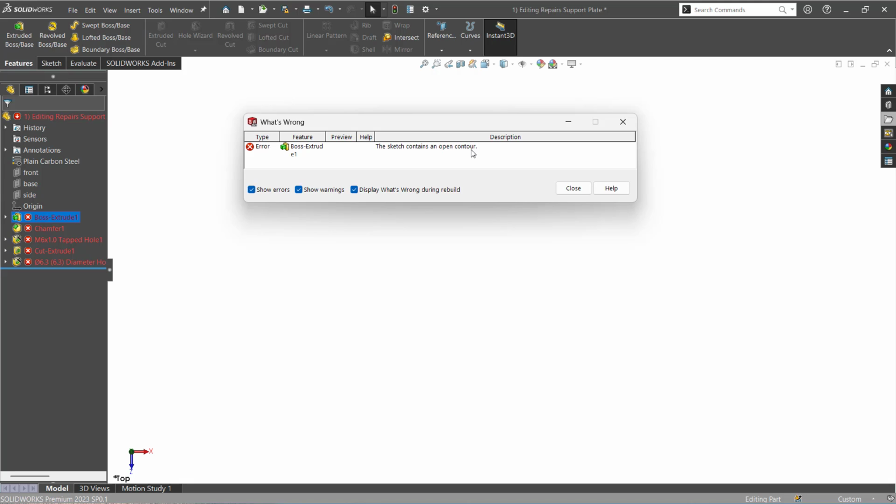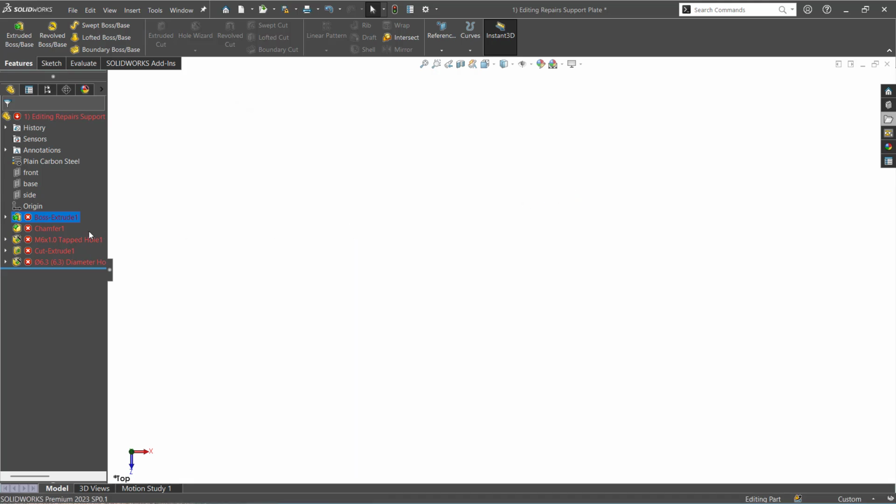So what exactly should I do to solve the error? We have to close the sketch. Good. In the description, it directly mentions that there is an issue with the sketch. So I need to deal with the sketch, not the feature. So use the drop down.